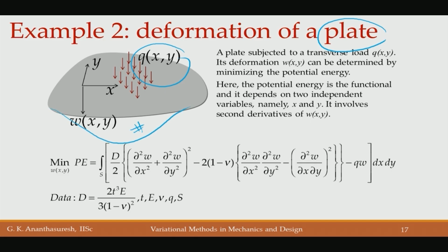Okay. The deformation that we denoted by w here as a function of x and y, then we get a differential equation. For that, we have to minimize the potential energy with respect to that function w(x, y), and in this case for a plate, from mechanics and geometry you can compute the expression for potential energy of a plate.